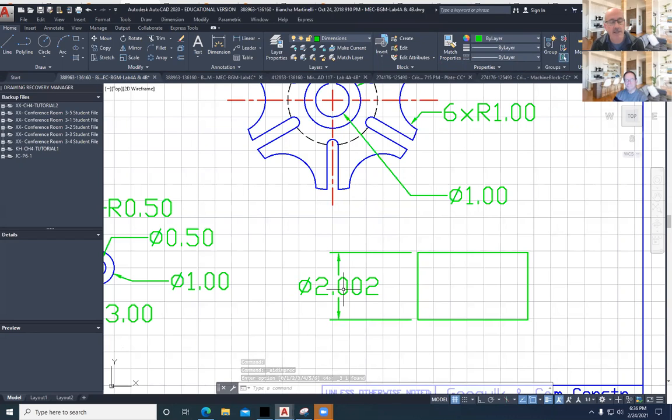And so if you talk to the guys at Woodward who make parts for helicopters and airplanes, they're right over here on Howard Street in Skokie, they'll tell you that they hold 0.0005, and it's very, very fine. A human hair or a piece of paper is about 0.003 thick, or 3 thousandths, tenths, hundredths, thousandths.